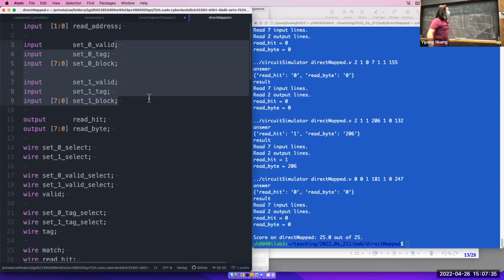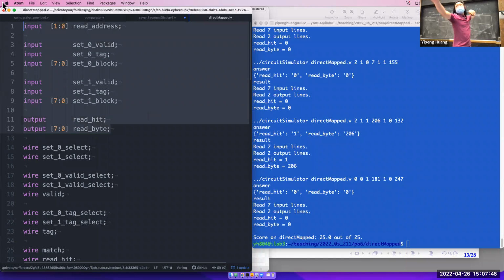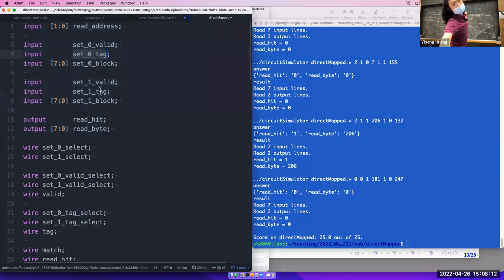So let's try figuring out what this is. All right, so first of all, what's the size of the memory addresses? It's already specified here in this description, right? Yeah, 2 bits, right? So very small memory addresses, just 2 bits. Can we figure out tag yet? Yeah, 1-bit tags, right? So you can tell that's 1-bit tags because the tag fields here are 1 bit, 1 bit.